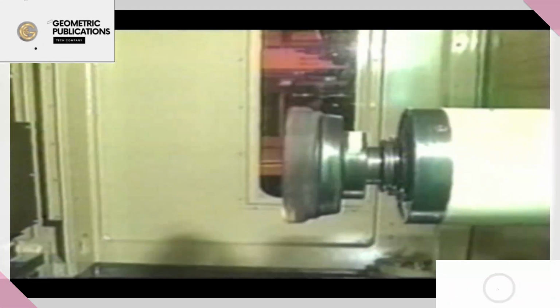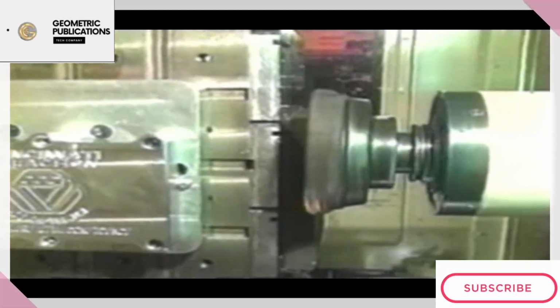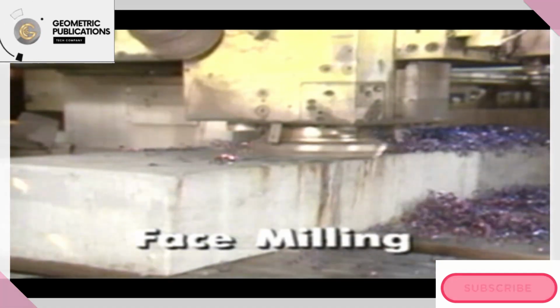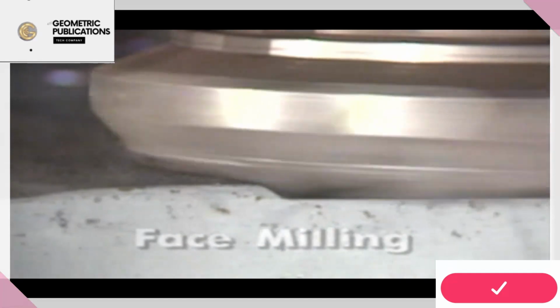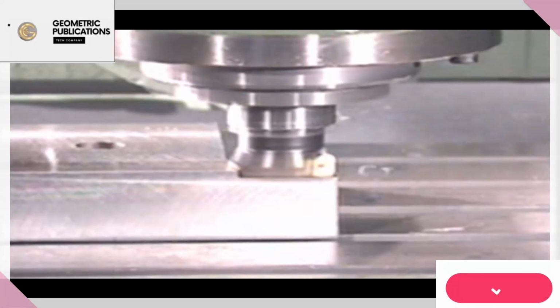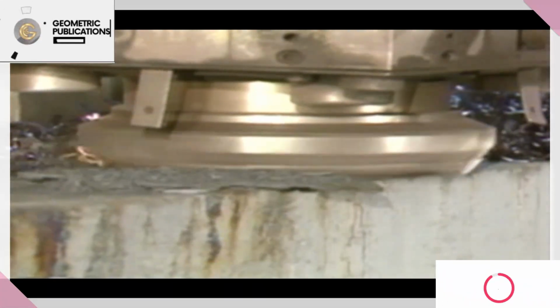Generating flat surfaces or flat surfaces with square shoulders is one of the basic objectives of the milling process. Face milling cutters effectively generate flat surfaces at high speeds with the spindle axis perpendicular to the work surface. Face mills range from about 3 inches to 2 feet in diameter.